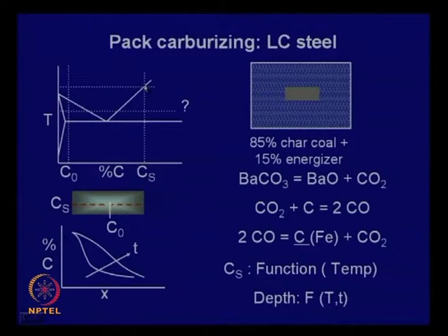So, this determines the surface carbon content, and the depth of carburization will depend on the diffusivity of carbon. At higher temperature, it has higher diffusivity. Therefore, the higher the temperature, the higher will be the depth of carburization and the higher the carbon content at the surface.